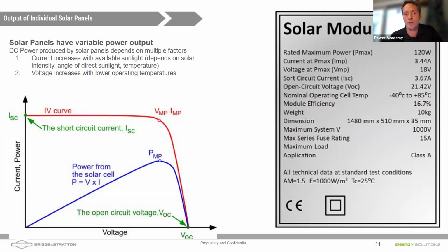And so what we want to do is maximize the power production of a panel. So if we draw a little less than the maximum amount of electrons produced, we'll still have a voltage. And the voltage is essentially the difference in electron density between the top of the panel and the bottom of the panel, right? And so we want to keep voltage high, but we also want current to be high. And so if we vary how much current we're pulling off the panel, it balances out that voltage, which is coming from the electron density difference, with the current.